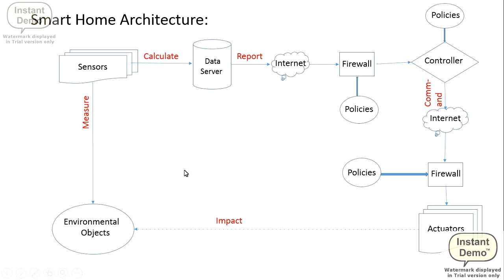So there will be other policies on how the data will be transmitted, what the rate of this transmission will be, and what the rate of the sensing will be. From the related work, we have decided on using data variance for measuring the transmission time. We know that transmission of data takes double the time of the sensing of data. So we will try to dynamically adjust this transmission speed according to the variance.